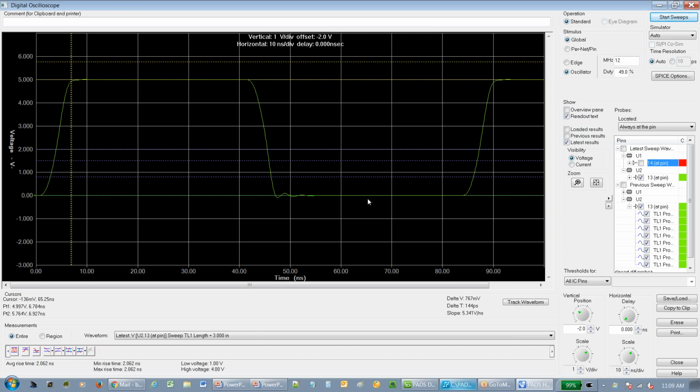But this, again, is what a lot of people don't understand: they're trying to do 2-layer boards to reduce the cost of their product. They're routing the power and ground on the board. You may put power planes on the top, or a ground plane on the top and the bottom, but it's not a very good reference because it's so far away from the reference trace. Plus, you're more than likely crossing other traces, and it's not a consistent reference plane. You need a very consistent reference plane in order for your signal to look this good, okay?